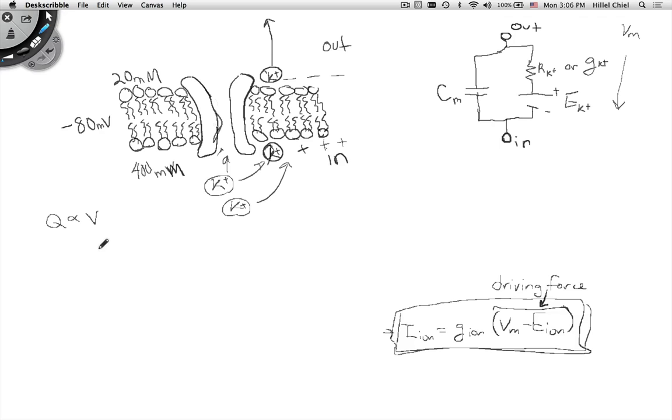So all of these things actually make perfect sense. Now, we had this clever trick. We changed V proportional to I into V equals IR. Let's do the same here. Let's have a proportionality constant, which we talked about already, call it the capacitance. And now we have Q equals CV. That's the fundamental capacitor equation, where C is capacitance. Now we talked about the fact that that's stable, and it could stay like that forever. But if we're interested in currents, we're interested in changes of charges with time.